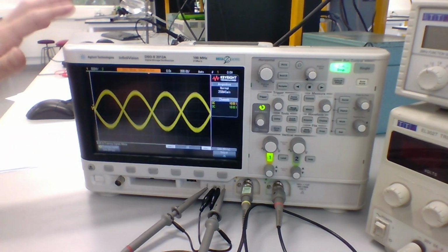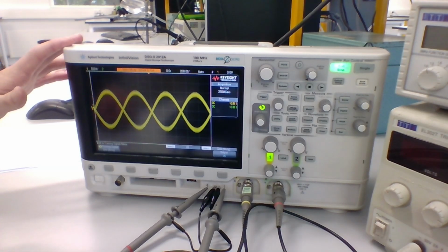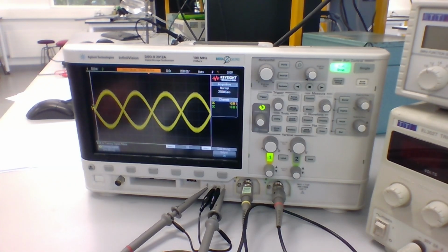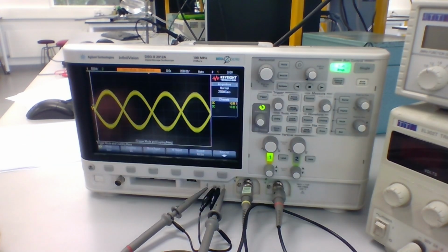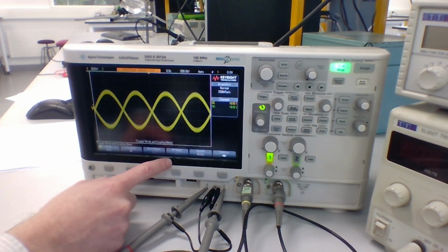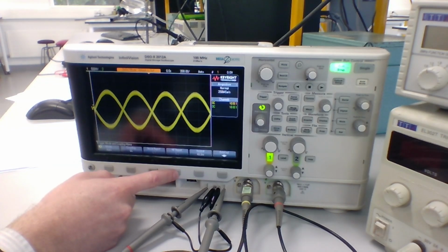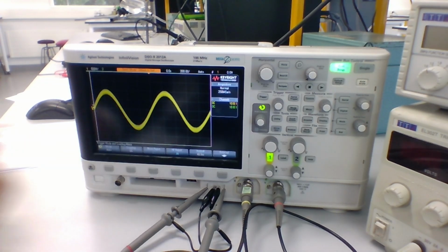On these oscilloscopes, there are a couple of ways we can deal with that. One option is using what's called the high frequency reject filter that's built into this oscilloscope. So if we press the mode coupling button, one of the options here is labeled HF reject, which is high frequency reject. If we enable that, what that will do is basically filter out high frequency signals.